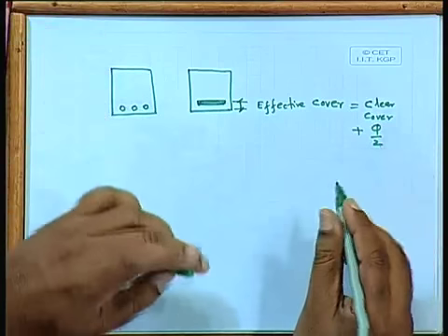So here we assume a certain diameter, based on our experience. Say this is the moment, so we know that this bar will come, whether 12 millimeter or 16 millimeter or 20 millimeter. We can assume that, because if you do 5 or 6 examples with different moments, you can immediately understand what type of bars will come, because at the end of the day you do not have much choice.